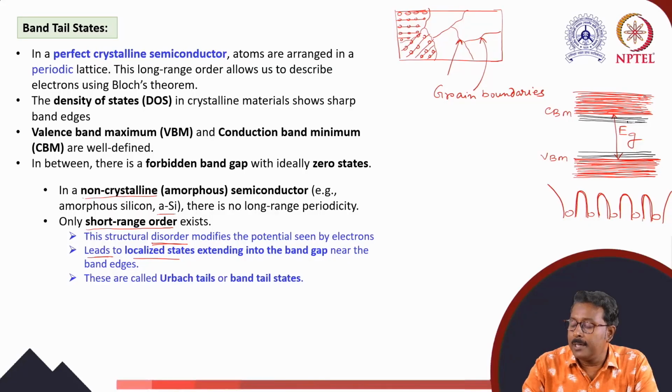Carriers in these states cannot conduct freely, just like in a conduction band. So carriers are localized or confined within this band. From one state to another, a carrier may move by a different mechanism called hopping, or thermionic emission and recapture emission, etc., but not like a free movement for electrical conduction like the carriers in the conduction band. That's why its name is localized states.